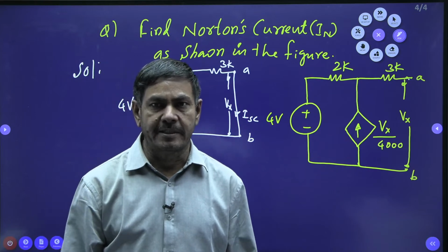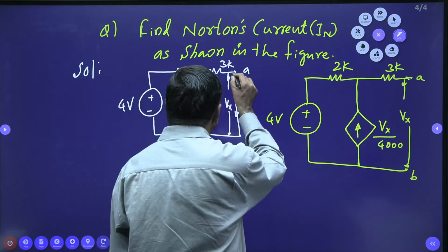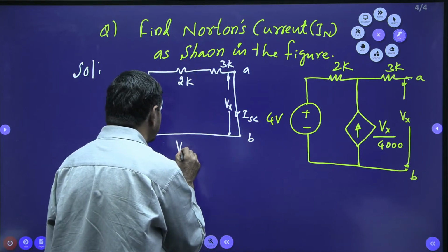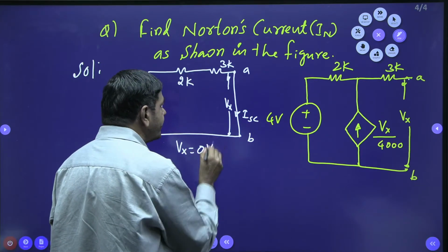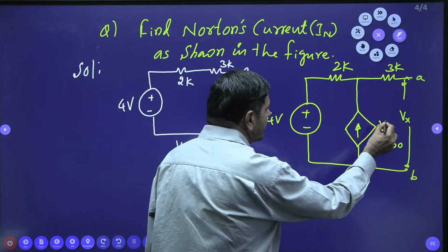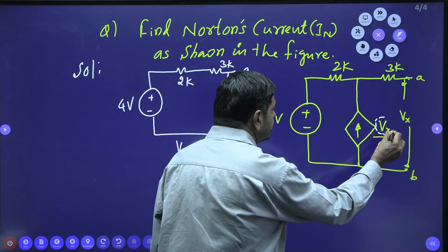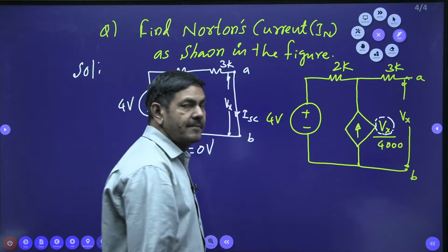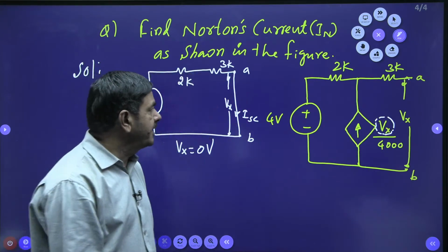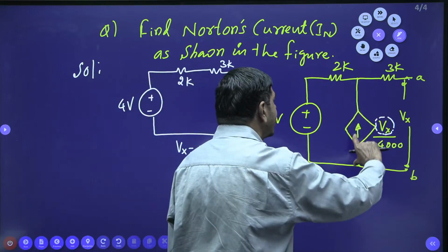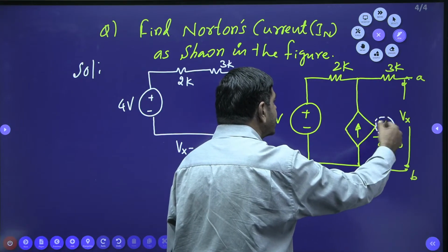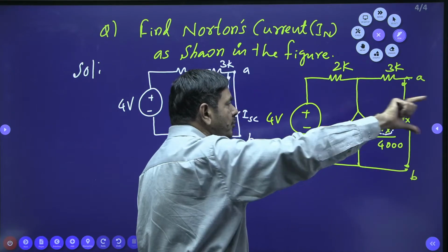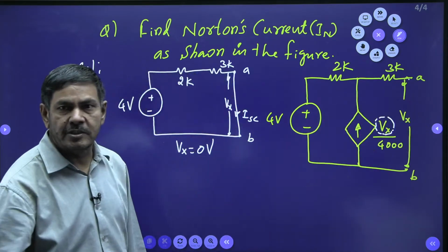0 voltage only. We cannot find any voltage across this. We don't have any resistor here now. So we can write Vx equal to 0 voltage only. In case Vx equals 0, this voltage becomes 0 only. If it is 0, 0 by something, 0 amperes. 0 amperes means what? This branch can act as an open circuit only. Current is 0. So totally you can remove this branch.